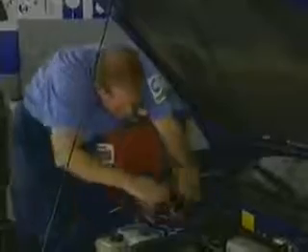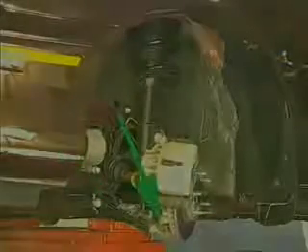If you're troubleshooting a caster problem on a front-wheel drive car, remember that some manufacturers do not provide for a caster adjustment on some of today's front-wheel drive vehicles. If the caster requires correction, an aftermarket kit is often available. Prior to attempting a caster adjustment on a suspension that does not have a factory adjustment, inspect the suspension for bent or damaged parts and replace them to correct out-of-spec conditions. Adding and removing shims on the upper control arms will correct both camber and caster on most rear-wheel drive cars.